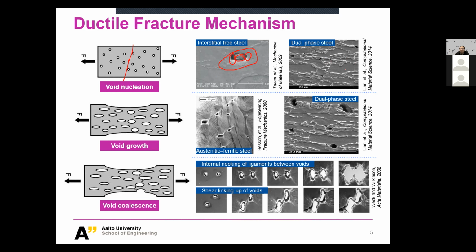Here you can see we have something like this color, green, and something a little bit lighter, those small islands. The lighter ones correspond to a hard phase. This one is much harder. They're still kind of steel. They have very similar chemical composition, similar crystal structures, but they behave differently.